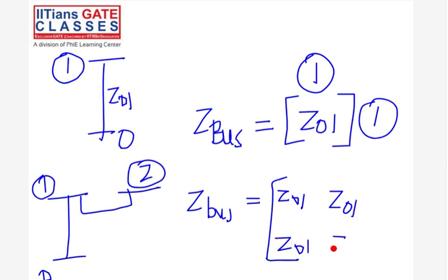And then for the new diagonal element, we will add whatever was there in the old diagonal plus Z1 to represent it. This is also a branch because it created a new node in the system. So basically we repeat the row and column of the node to which the new branch is getting connected, and then add the value to the diagonal element. Is this clear?